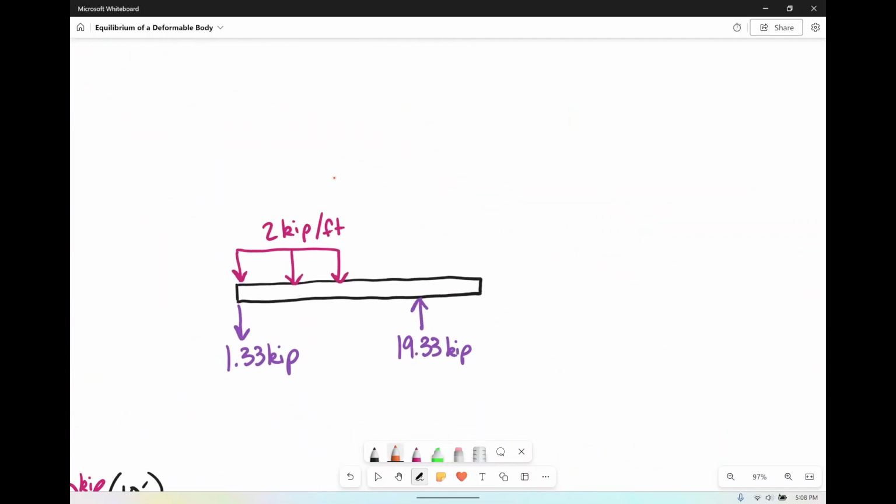So again, we have our normal force going out from the face, we have our shear force going down, and we have our bending moment, probably shouldn't have cut through that end, but whatever, going counterclockwise. It's definitely good to put distances on this. That'd be a great idea. So we've got 2 feet from the BY over to the cut. It's 6 feet from A to B, and 4 feet is the length of our distributed loads.